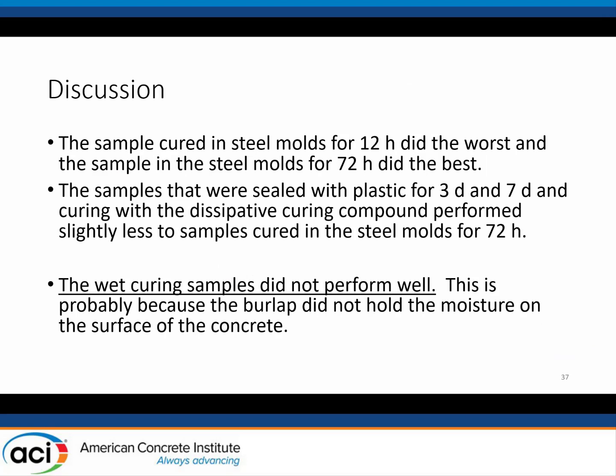The sample that was cured in the steel molds for 12 hours did the worst. For 72 hours was the best. And the samples that were sealed in plastic for 3 and 7 days did a pretty good job. But also those curing compounds, they also did a good job. And we'll talk more about those coming up.